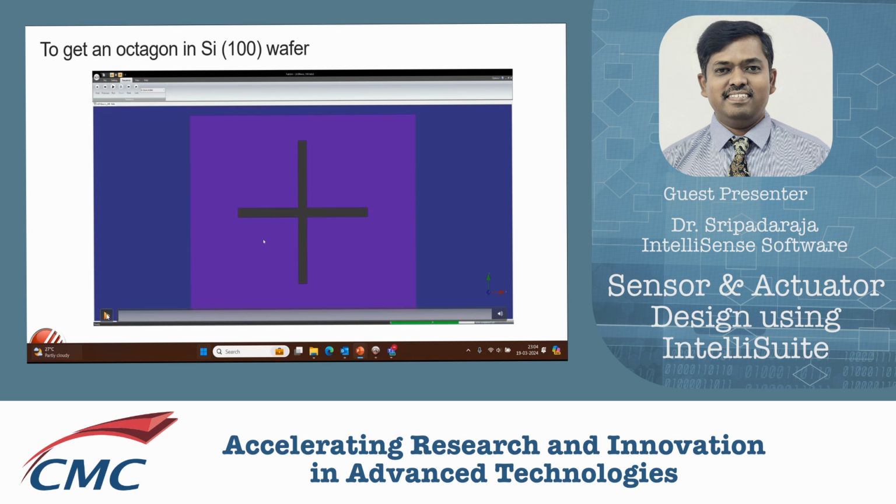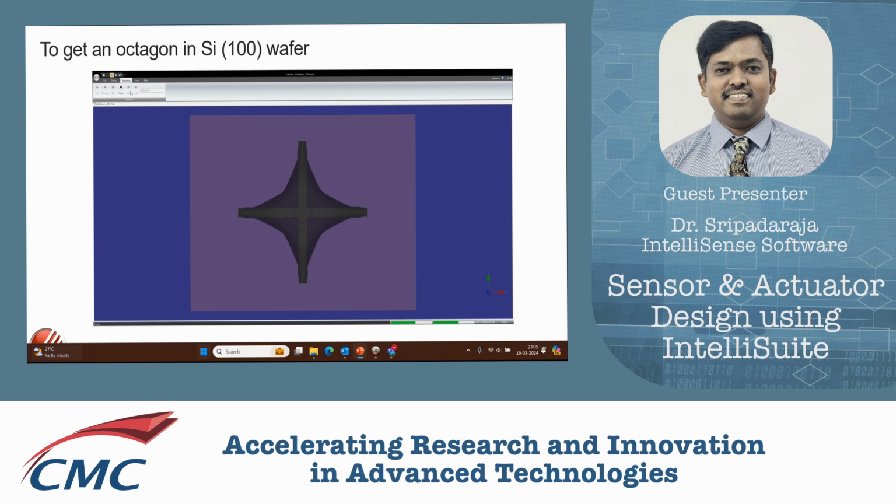Moving further, we try to create an octagon structure on a silicon 100 wafer. So here what I'm trying to show you is that a plus shape mask is used to create an octagon structure on a silicon 100 wafer. So what I'm trying to tell you is that you can do a lot of mask optimization within the software to achieve the desired profile of the device.